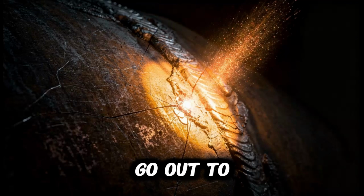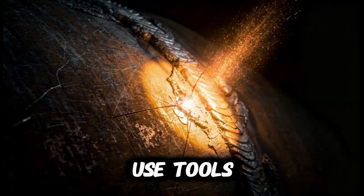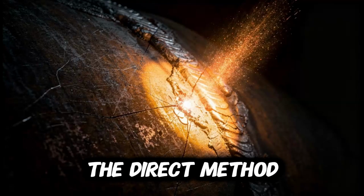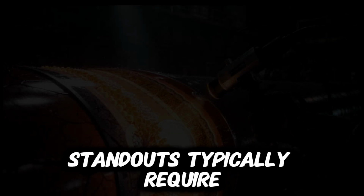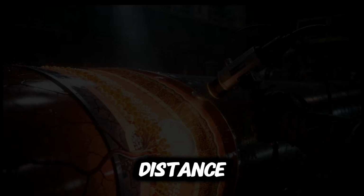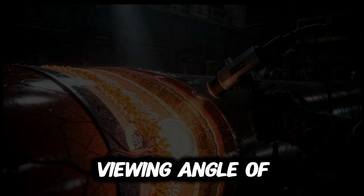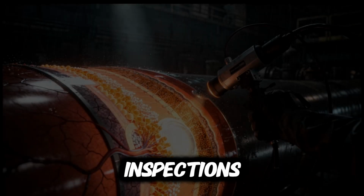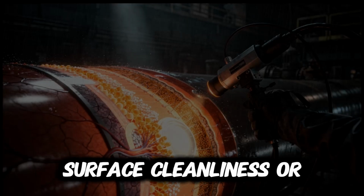So when we actually go out to inspect, how do we decide whether to look directly or use tools? We split the approach into two modalities. The direct method means unaided observation within strict geometric constraints. Standards typically require a maximum viewing distance of 600 millimeters and a minimum viewing angle of 30 degrees. It is used for immediately accessible inspections, basic dimensional control, and verification of surface cleanliness or corrosion.